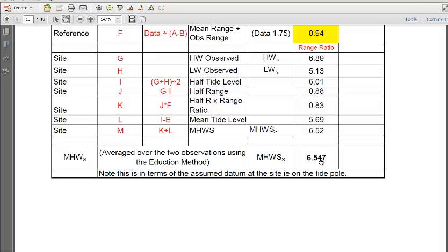It is thoroughly recommended that two benchmarks on solid land adjacent to the pole be established, and that the datum be established from the pole onto those other marks, so that the benefits of this work are not lost.